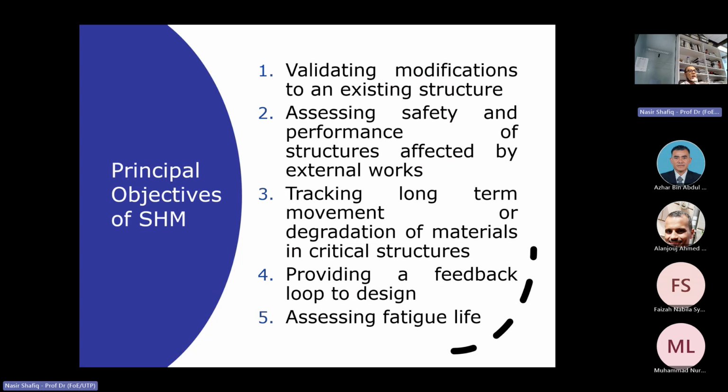So from there we can say the principal objectives are validating modification of an existing structure, assessing safety and performance of a structure affected by external work, tracking long-term movement, degradation of material in critical structure, providing a feedback loop, and assessing fatigue life, right?